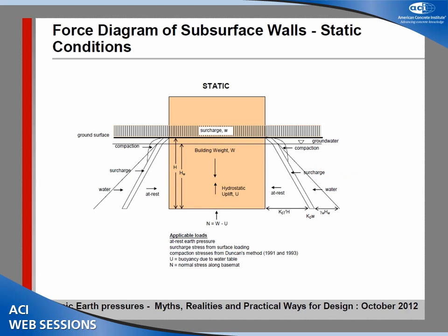In terms of the introduction and background, this figure depicts the type of loads that are acting in a partially embedded structure. This structure is assumed to have some sort of liquid inside, and under static conditions, in terms of lateral soil pressures, the pressure that is acting is the at-rest pressure, and I think there is really no controversy about that.